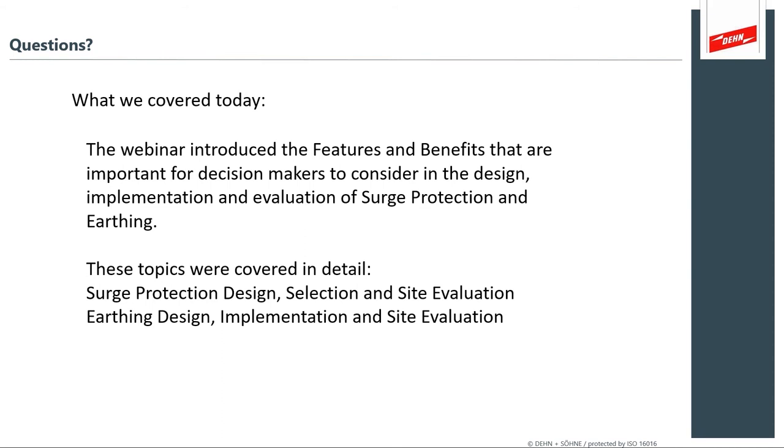Excellent. Those two factors are exactly what is considered. And remember, the IEC has the conservative assumption that 50% of the lightning current is distributed into the soil and 50% is diverted back into the electrical installation. So in other words, if you design a system for LPL 3, which is a 100 kA lightning strike, the IEC assumes that 50 kA gets distributed into the soil, while 50 kA might be seen by the surge protection devices. So you need to make sure for this LPL 3 design that you have a surge protection device that can handle a maximum of 50 kA lightning current.